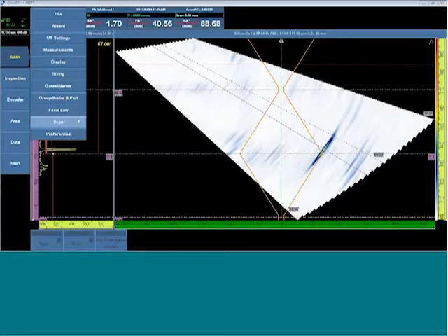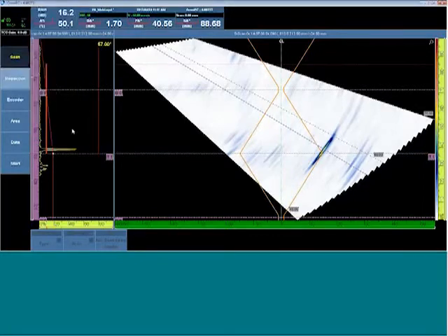the focal laws. So one of the things we do to convert this to a recorded inspection is first we'll set the one-line scan type as a one-line scan on an encoder. When this happens, we'll see the small icon at the top left corner of the screen change from a clock to an encoded inspection.